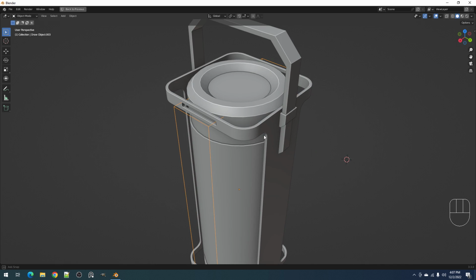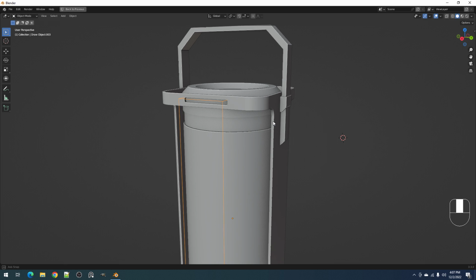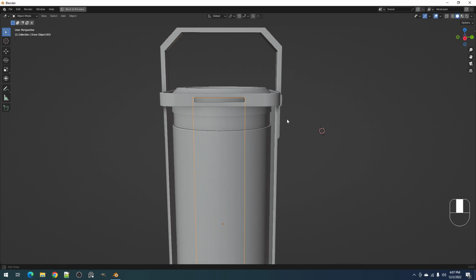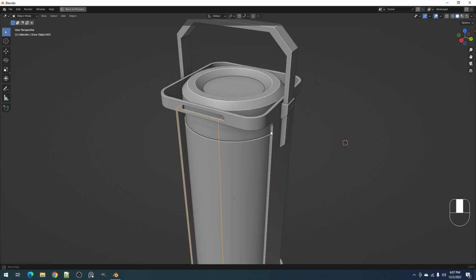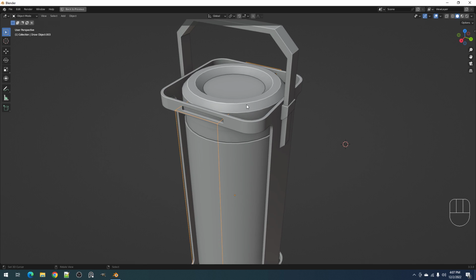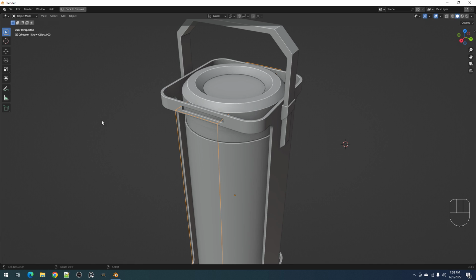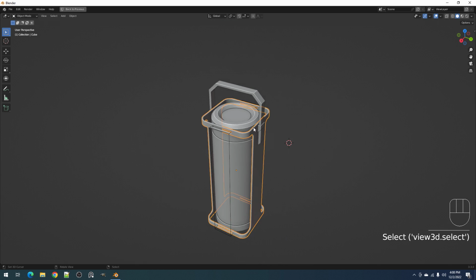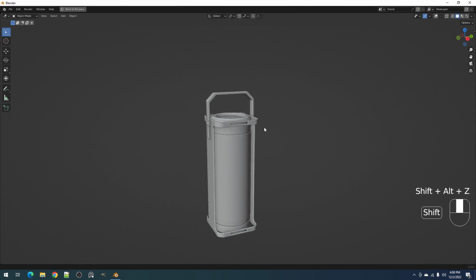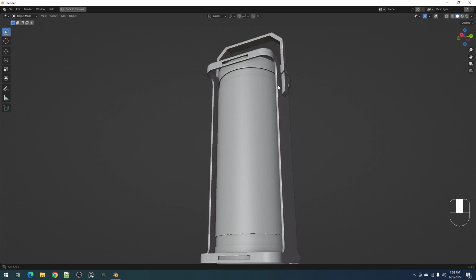So in order to affect the previous source target with the Boolean or draw, you must keep selecting it. After the draw operator and extract faces operator, the ones that are actively selected are the resulting objects, which is the draw object and the extract object. So in order to draw on this again, I have to select it after the draw operation and continue drawing on it.